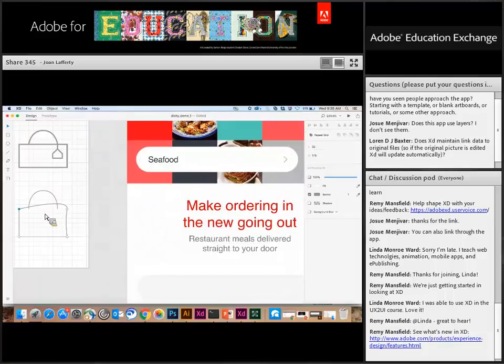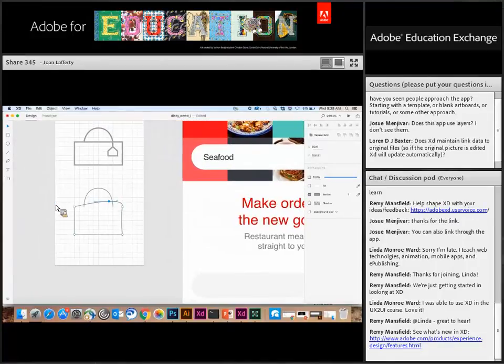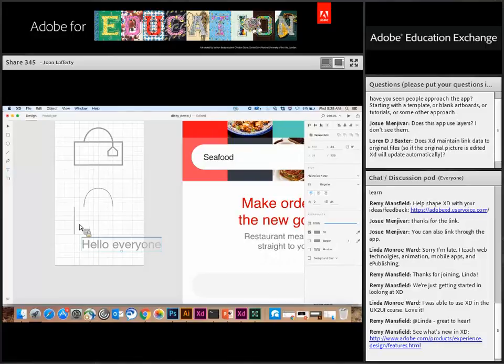And then one quick thing about text that I don't think is always the most obvious. With our text tool, if you have the text tool selected and you just click on the canvas, what you get is point text. If you resize that, it just resizes that entire piece of text. If you want area text, then you have the text tool selected and you click and drag the area where the text should live.